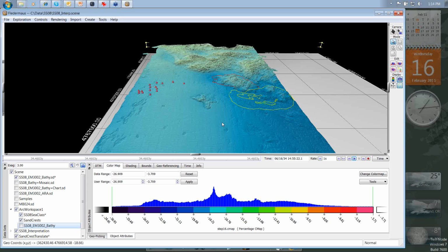All right. What's the maximum XYZ data Fledermaus can handle? Other than 10,000 by 10,000 grids, you must know that we do have a limitation of 10,000 by 10,000. In 7.3, it is going to increase. Doug, did you have any other comments on that? It's the XYZ data itself, it doesn't really matter. The 10,000 by 10,000 is the rows and columns. So depending upon your bin size, you can accommodate larger or smaller areas depending upon the resolution you want, or you can build multiple blocks across an area, and that's another way to do it.